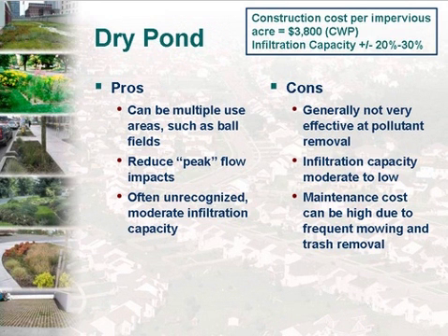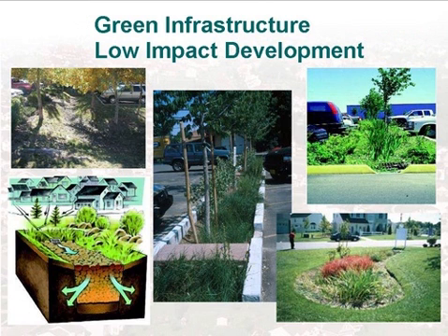And looking at the cost for these maintenance ponds that are dry ponds, about $3,800. That's your base construction cost, not considering the high maintenance of mowing the turf. If you don't have a sediment forebay in front of it, you're coming back every 5 years and dredging out the sediments, which is an extremely high cost to incur by the municipality. Yeah, absolutely. So I think that's a pretty good summary point on that.